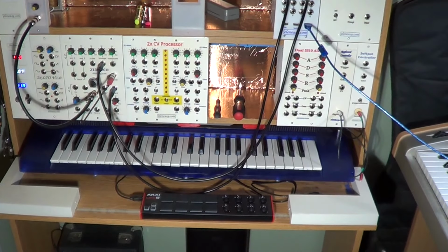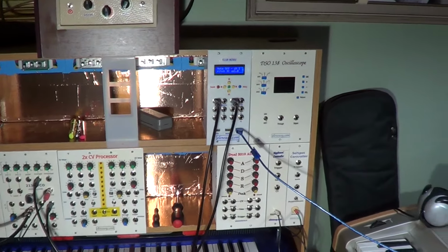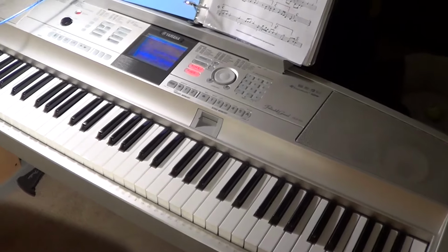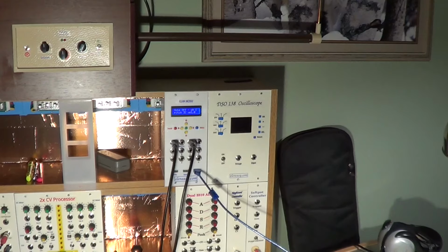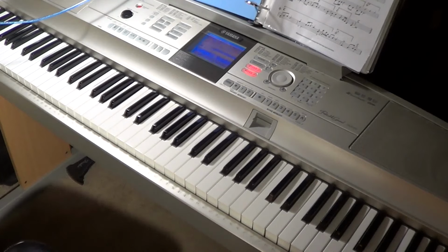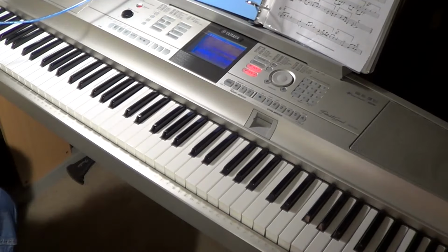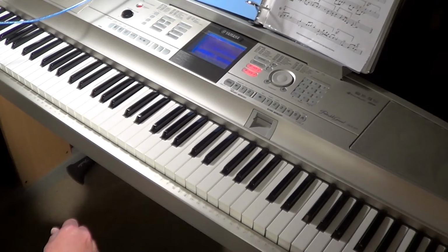Now I have disconnected the LPD8 and instead I have connected to the MIDI module the DGX505, and I will try to use that to play something. The MIDI module right now has the control voltage connected to the VCO and the gate also connected here to the control voltage for the VCA channel for the triangular wave. This way, every time I hit a key, the gate will go up and we will hear the triangle wave coming out directly with no modulation and so forth. Let's see what this brings us. I have turned down the volume of the keyboard itself, so the only sound is the one coming from the synth.